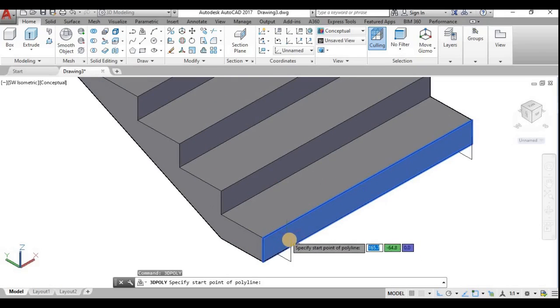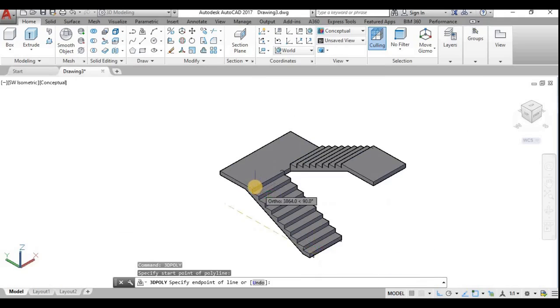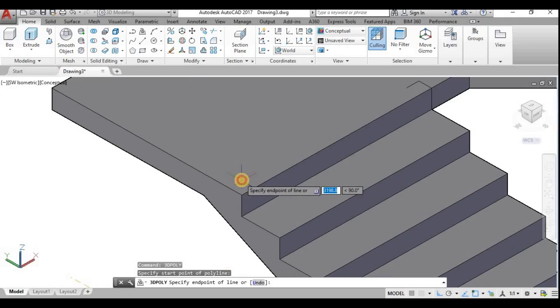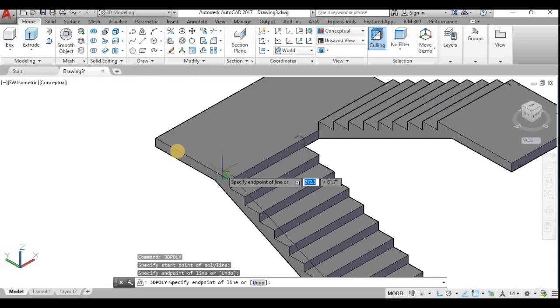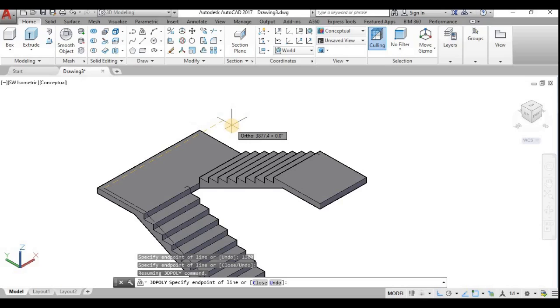I have some marking here because this handrail will start at some distance from the steps. So I have marked here and made the marking there, and every place there will be some distance from these steps. I have made 100 mm spacing for each and every outside of the handrails.